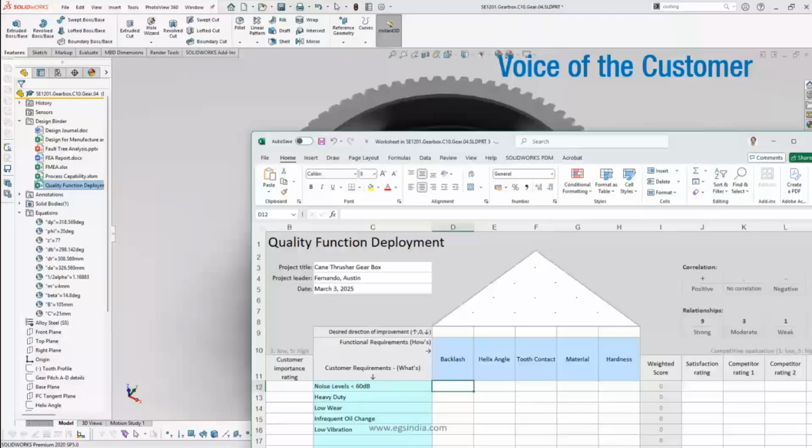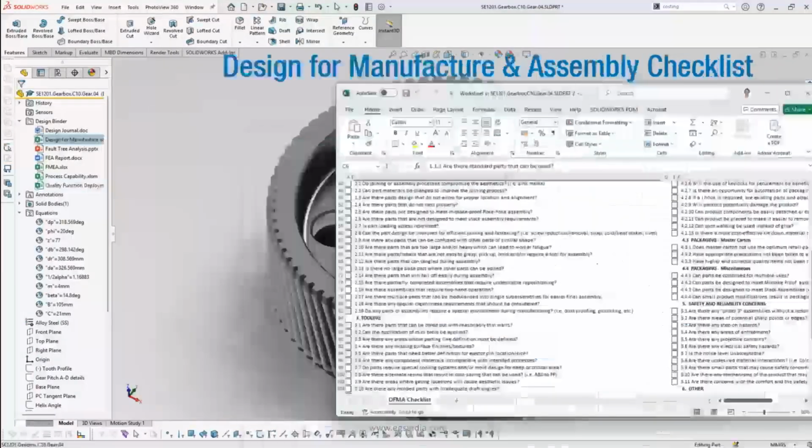Okay. The next is the design for manufacture and assembly that we talked about in the assembly objectives earlier in the DFQ&R process. Put together the checklist, build upon the checklist based on issues that have come from the manufacturing, from inspection, from your customer, and build this live database in terms of compliance checklist so that adherence to that at the part level, at the assembly level, at the subsystem level, at the system level can be monitored, approved, and released.